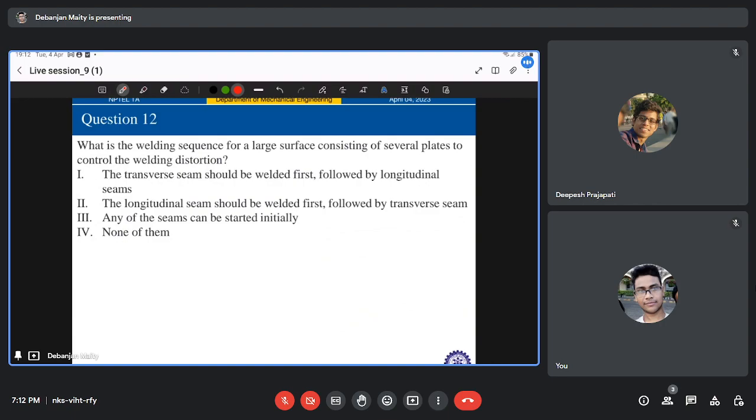The fillet, whatever you are using, that can be of minimum size, right? Also the distortion can be minimized by proper assembly procedures, such as presetting the members to compensate for angular distortion, or assembling the weldment so that it is nominally correct before welding, and then using some form of restraint to minimize the distortion from welding. And finally, of course, there is sequencing of welding to balance the heat input and create some offset in your shrinkage or distortion.